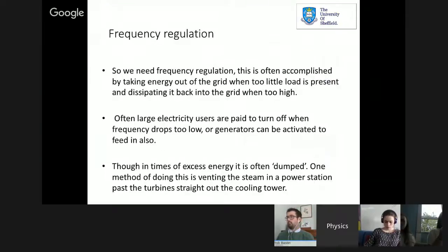So, in essence, you can get why everyone's running at this 50 hertz. As you can imagine, all these mechanical components are tuned to run at that 50 hertz, so if you get a slight deviation, all of a sudden you get efficiency losses and even quite dangerous problems. If you're running two generators and they're not syncing into the grid, you've got to sync those generators roughly at 50 hertz, otherwise one generator might be feeding straight back into another one, and all sorts of things are happening. And it isn't just about frequency, it's about the level of voltage, all sorts of things.